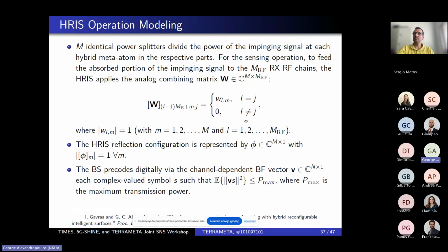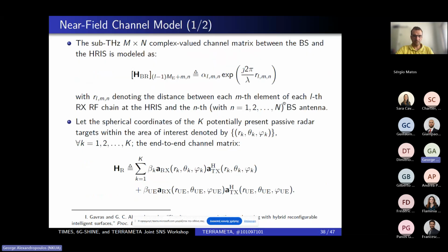The reception part of the RIS is modeled as a DMA-like dynamic metasurface antenna receiver, with analog combiners at the end of the day, for which we have used models for the included unit cells. Of course, there are certain works right now extending this to incorporate all the losses that happen within the waveguide.